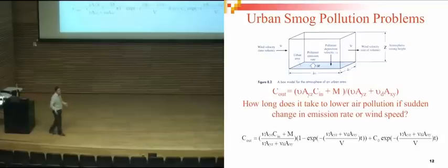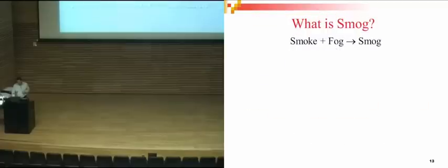So again, when you look at these problems, you're going to have to ask yourself, is this a steady state problem or not? Are we looking at a change, dC/dt, or not? Okay. So that's a way to solve our mass balance equations.